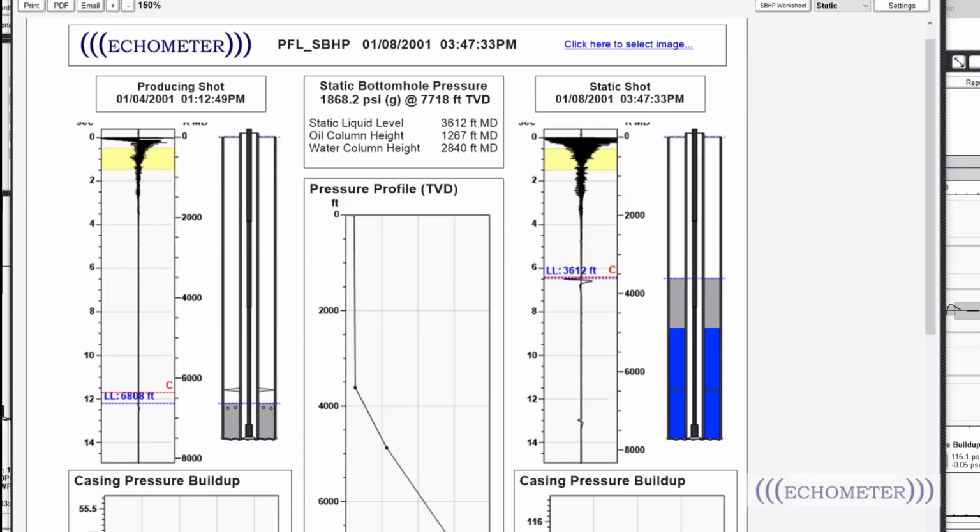Let's see, we have a few questions. Anil is saying, in one of the graphs you have shown, I think I already did that. And Juan Carnaque is asking how to correctly calculate the liquid level column in a well with very high submergence. Sometimes the software calculates a high liquid column, and at other times it calculates a high gas flow. The liquid level signal is located at almost the same depth in similar production conditions. And probably Dr. Podio may chime in on gas buildup, which very likely affects the calculations.